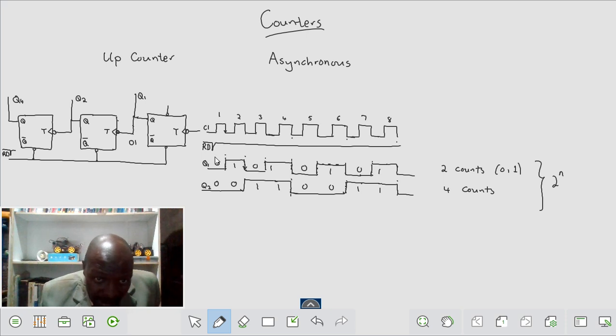Okay, at any given time we want to reset. Let's suppose our initial count, maybe the Q4 had been a 1. Okay, at that point of resetting, that 1 would go to a 0. Okay, so then that there sees the leading edge, that Q2 is feeding that clock, so it doesn't say anything, so it will ignore everything all the way up to when Q2 goes from what? From 1 to 0, which is seen as a what? As a trailing edge, and therefore you know it's a T type, so it will just toggle.